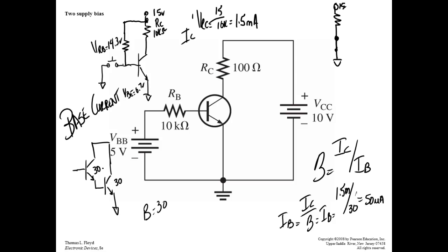So that means if I put 50 microamps over here, take 50 microamps and multiply it by 900. Pretty good current gain, right? So we do this a lot, especially if you're going to use something that can't provide a lot of current. By the way, this is called a Darlington pair.